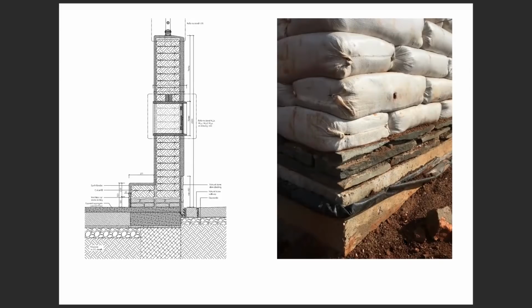On the background there, you can see the real picture of the buildup of this. We are using a stone DPC, which is a very hard black granite, and we are bonding it with cement mortar, and the gaps we're filling with loose sand. And this has already shown from the tests that we've done that there's really no moisture rising through this kind of material.